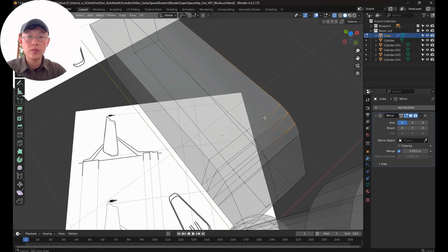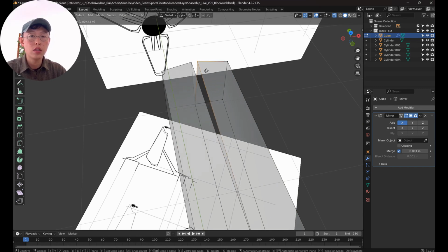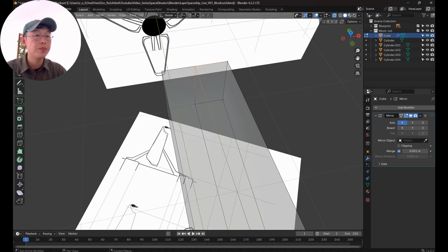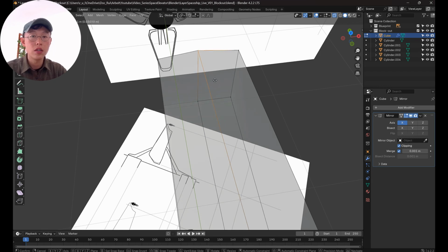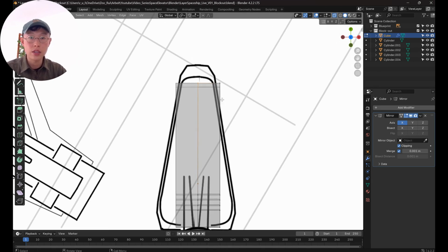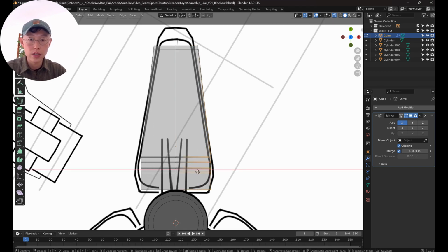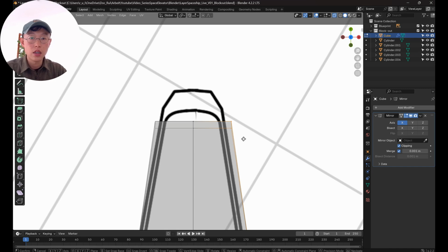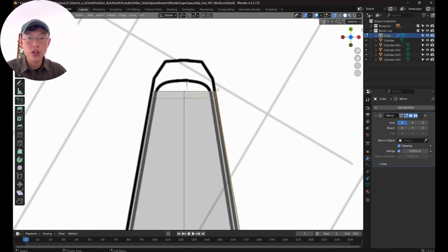And one thing to pay attention to is that now it's kind of open, right? You can overlap the vertices and have a gap by pulling on it. And when I click on clipping, now the middle part is connected, and that is kind of important because otherwise later you're going to have a lot of problems if it's open or the vertices are overlapping. It's just really rough technical mistakes, I would say. Cool. Let's do this round shape.